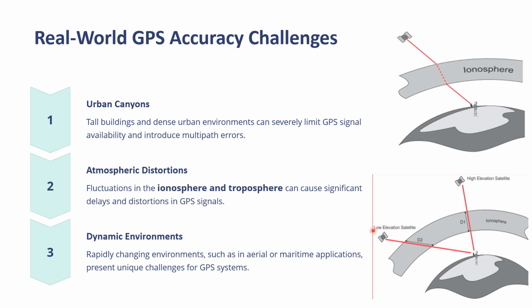Elevation problems can also introduce multipath effects. Suppose there is a low elevation satellite and a high elevation satellite. From the two satellites, the signal comes through the ionosphere, so path error will be introduced, which can introduce error in the positioning measurement of that point from satellites near the reflecting surface. These points have to be mitigated by addressing the problem.